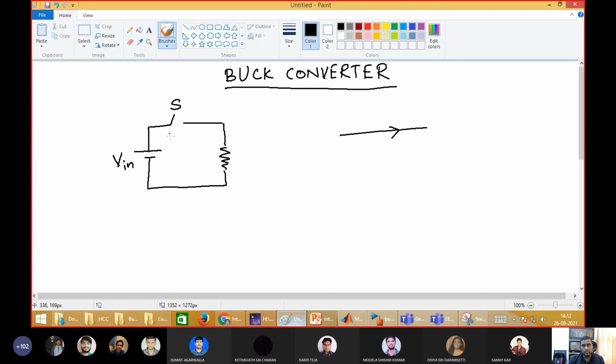So if this is a switch, you must measure the voltage across the switch. You must measure how much current is flowing through the switch. Since the switch is in series, all elements are in series, so this current is iS. Always remember there are two symbols. One is capital letter, another one is small letter. Capital letters are used for DC where the value is not changing. So it is DC quantities. Now small letters are used for instantaneous values, where it is changing with time.